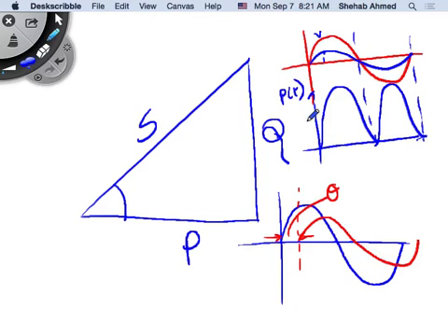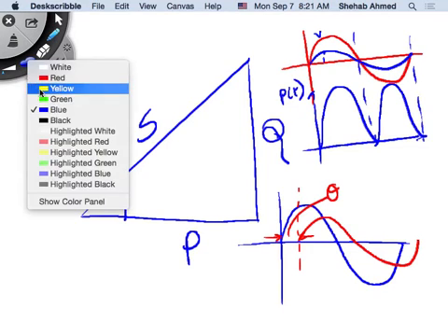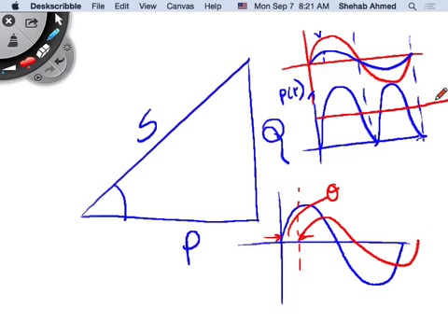Does it have an average value? It has an average value, somewhere maybe here. You can calculate the average value. Basically, it's 1 over the period integration of this waveform over the period. It's the area under this curve, which you divide by the period. So it has an average value, and it's always positive. That means power is always flowing from the source to the load. I'm talking about instantaneous power, which is always flowing from the source to the load.